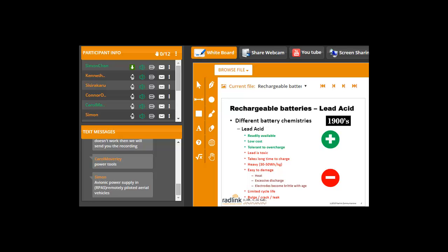And because of the high energy and power densities in a small package, we're talking about 5 to 8 times the energy capacity of a lead acid battery in a small amount of material, that can create a big mess when you have a small fault, maybe a short circuit inside the cell or something like that. You could have smoking circuits and burning circuits very quickly. However, if you stick to the design guidelines for lithium batteries, they're actually quite safe. Let's explore this a little bit more.